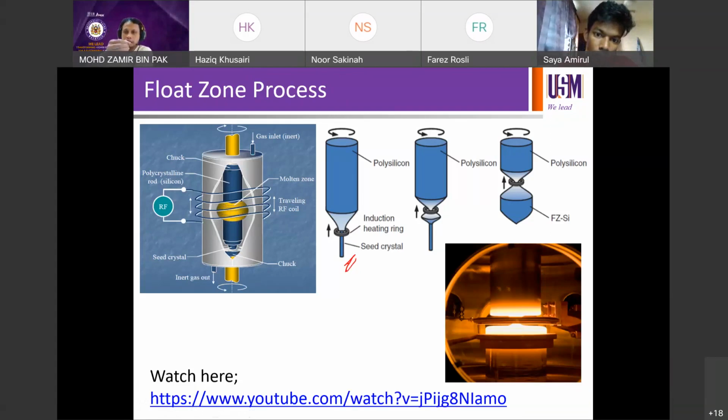So it's moving and melting the zone. So when it moves up to the middle, you can see it's melting the zone there. That's being melted at the same time. So when it melts the part in the middle, the part below is actually already crystallized. So the region below, the previous region, because it moves from the bottom, the previous regions are already crystallized and purified, if you like.